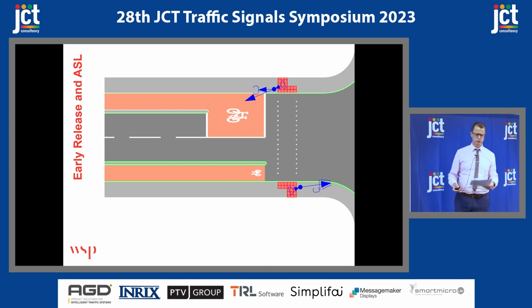One step up on the LTM 120 list of cycle facilities from an ASL is early release. This is generally used with an ASL and gives a head start to cyclists who are waiting when the low-level cycle signal turns green. It gives cyclists some separation in time, but it provides nothing for cyclists who arrive while the signal for other traffic is already green. Cyclists who arrive then emerge from their segregated cycle lane straight into conflict with other moving traffic. This, I presume, is a key reason why LTM 120 advises that ASLs are not suitable for approaches with high flows or that spend more than 30% of the cycle time on green.